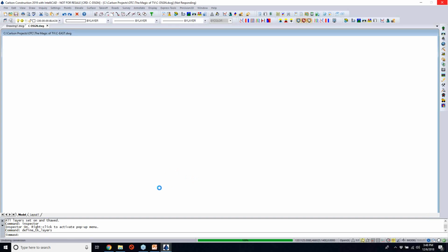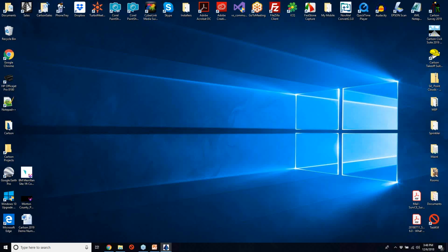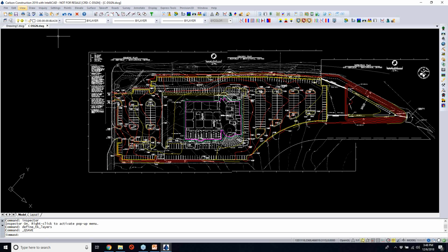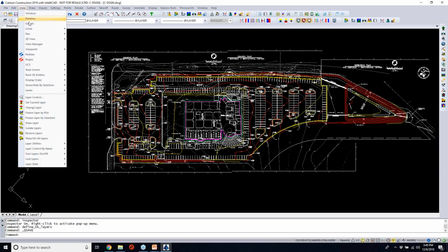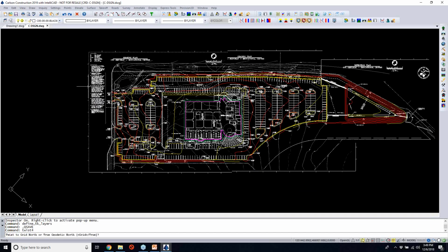And then when I want to bring this all back together and do my inserts later on, I can undo that twist screen through view, which is where I did it all right here. So I said, do a twist screen, line, polyline, or text, and I simply said, make this line, for example, due east. Well, if I want to restore due north, I can just do that and set it to grid north.